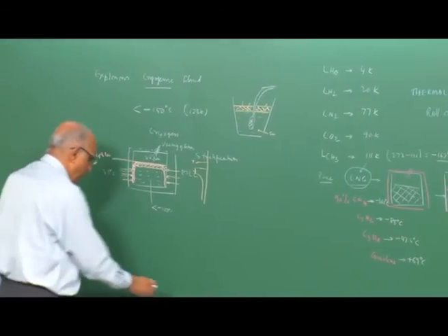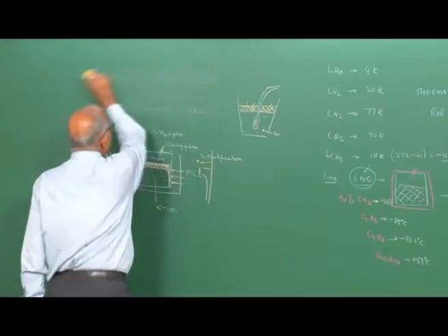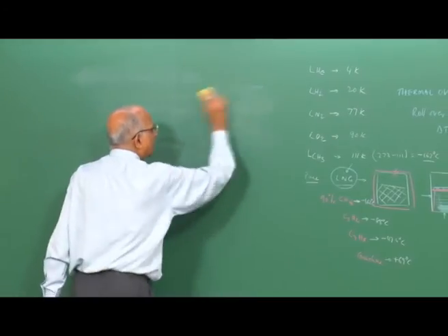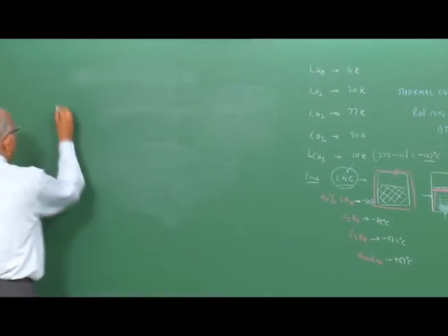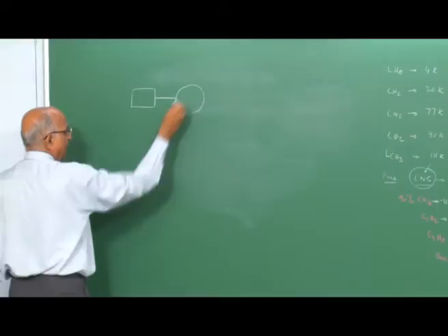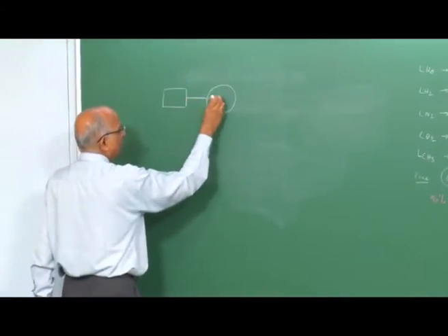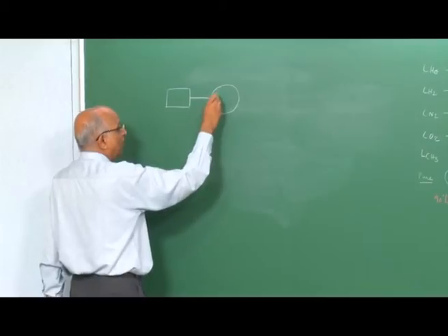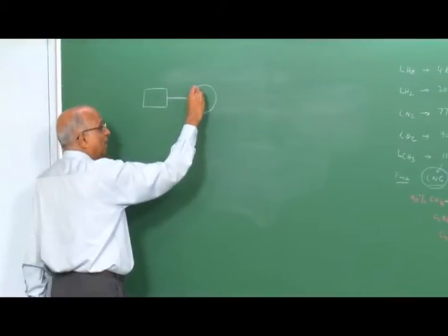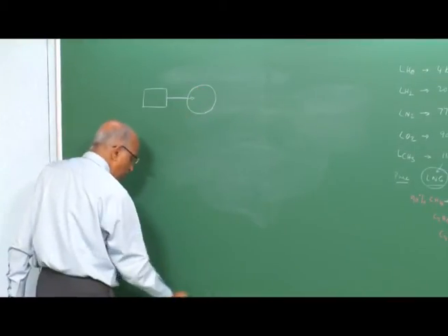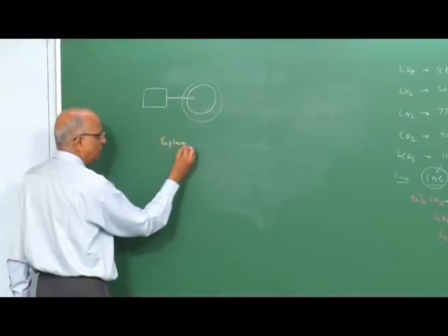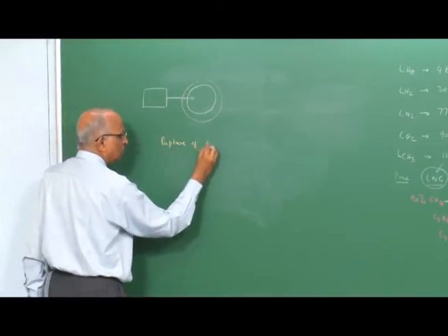Let's move to the next topic, which is something similar. Why cryogenic fluids? Any pressure vessel can explode. Like for instance, I have a compressor, and the compressor is used to charge a storage vessel of air. I keep on supplying air at higher and higher pressure. By chance, if my regulation system is such that I pressurize it to a very high value, this storage vessel could just explode, could just rupture. Therefore, we would like to find out what is the energy release during rupture of a closed vessel.